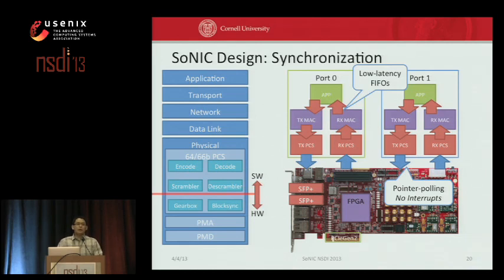With this technique, we created a small data structure which is shared by software and hardware, and where only hardware can write. So software is basically polling the values out of the data structure to find out when to start the next DMA transaction. This way is better than interrupts because there is no overhead associated with interrupt handling routines. And this is better because 10 gigabit Ethernet requires a continuous bitstream. That means there's always data to be transmitted between software and hardware.